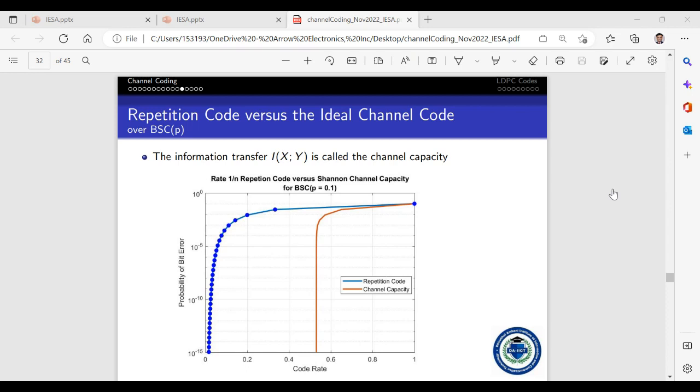So I would say that is one of the biggest technological challenges. And there, for example, there is a technology called massive MIMO that is being increasingly adopted in 5G and 5G-type networks. In 4G, you may have heard of MIMO already, where they use maybe at the most 8x8 MIMO, 8 antennas at the transmitter, 8 at the receiver. Typically, it is even less than that, maybe just 4x2 or 2x1 and like that.